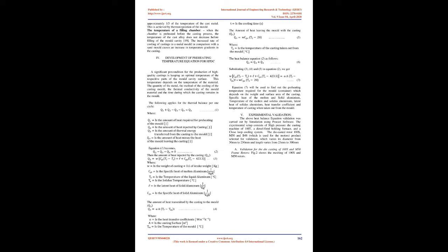Pouring temperature generally varies from 650 to 800 degrees Celsius. Generally, better fluidity at higher temperature is connected with preheating, which is done to remove the possibility of formation of temperature gradients. If we increase the preheat temperature beyond a particular range, then it may affect the die coating and may create defects like rough surface finish. Also, if the temperature is reduced considerably, then this may cause a chilling effect, which in turn leads to less solidification of the core, and due to this difference in solidification rate, defects like solidification shrinkage may occur, decreasing viscosity.